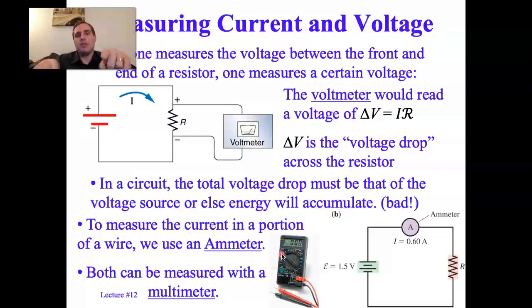It'll give you a little beep if the circuit is not connected continually. Okay, so anyway, there's a beep in one situation. There's not a beep in the other situation, whether it's continuous or not. Okay, so again, these multimeter devices are very useful for basic electronics troubleshooting. Okay, but you just switch the mode there to switch between voltmeter and ammeter.